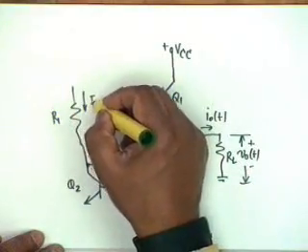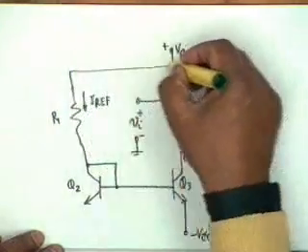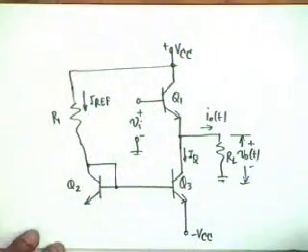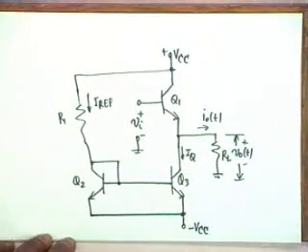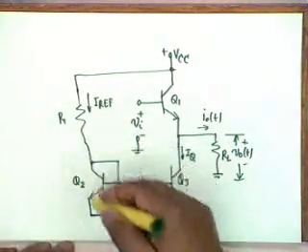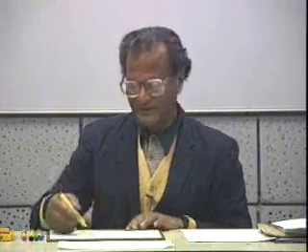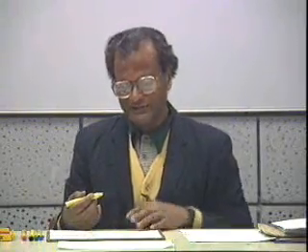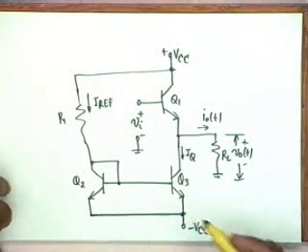The current through this is Iref, the reference current, and this naturally has to go to plus VCC. Okay, this is the transistor and the emitter is connected to this emitter. I have shown a simple current source, but it could be a Widlar source depending on what value of IQ you want. If you want very low as compared to Iref, then you use a Widlar source, another resistance here.